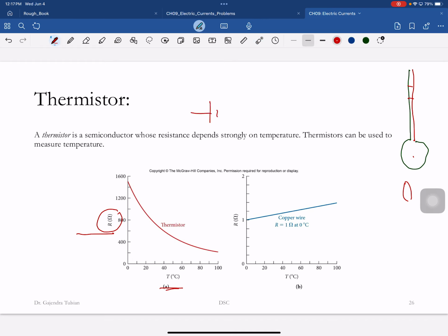Well, what we do is we use a thermistor and connect it to a 10-volt battery, and as the temperature rises, resistance decreases, and current in this thing will increase. So current is the proxy for temperature. Use those in engines? Use those in engines to check engine temperature.